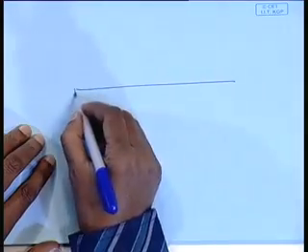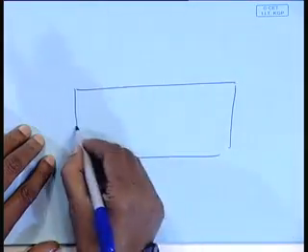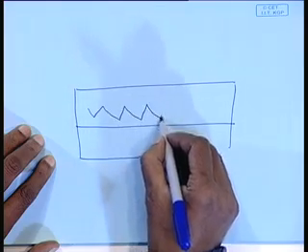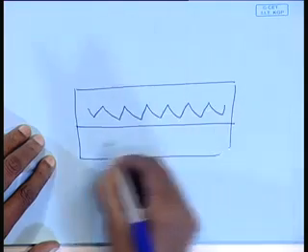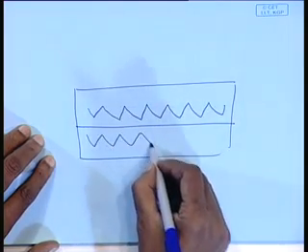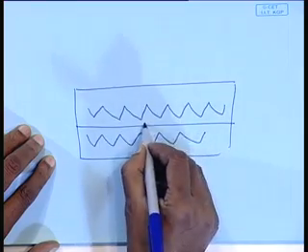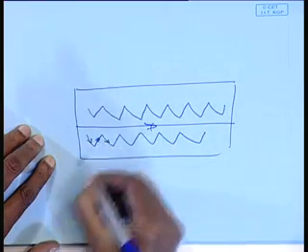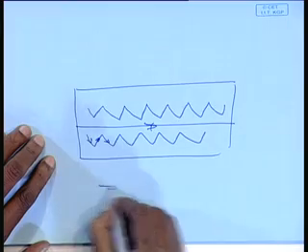So, these ultrasound probes are used in a zigzag fashion. This is the weld line. The ultrasound probe is moved in such a fashion on both the sides of the weld zone. Why is it done that way?